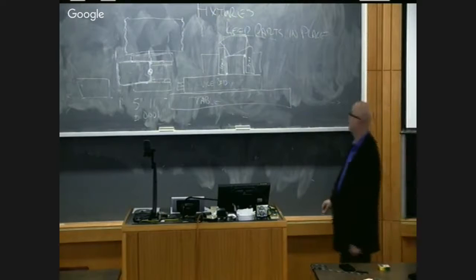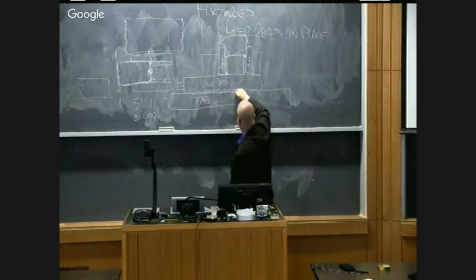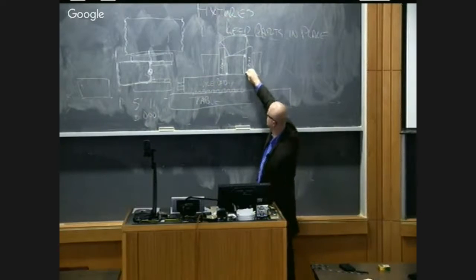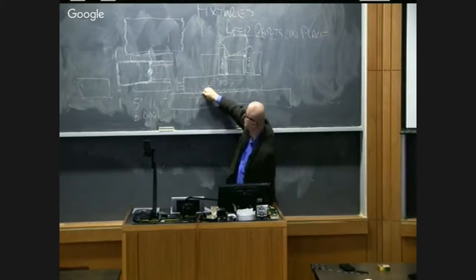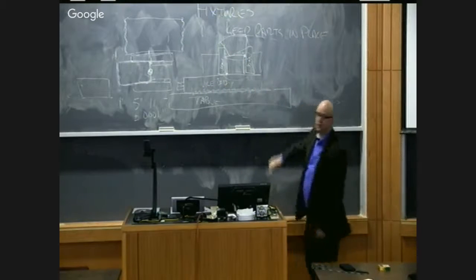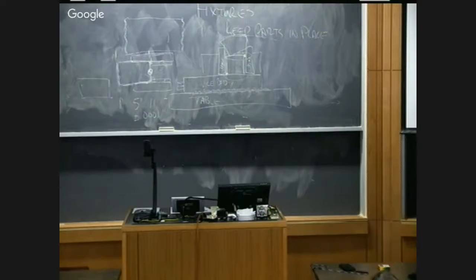Now, you can play with this interface all day long. If there's chips here, you're never going to get it right. The vise could have chips underneath it. Those vises sit on the table for weeks at a time sometimes. Sometimes we find a bunch of chips underneath it because whoever put it on the table wasn't careful.